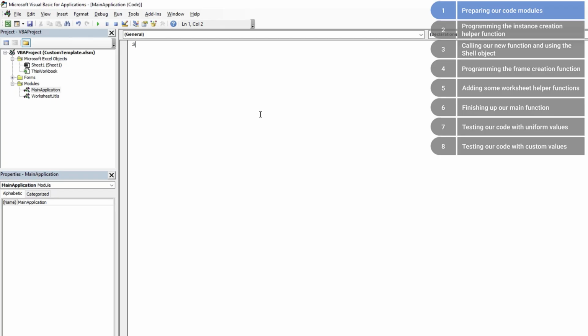Here, we'll add a new subprocedure called create SAP model. This will be the equivalent of a main in Java programming, for example. It is supposed to be where our most high-level code runs, and we'll be calling most of our specific auxiliary subfunctions here. The goal of this is, besides keeping our code somewhat concise, to easily understand the whole workflow of our function at a glance.